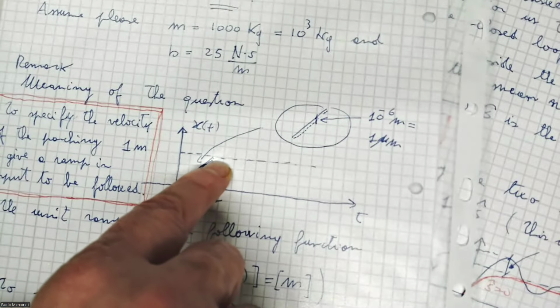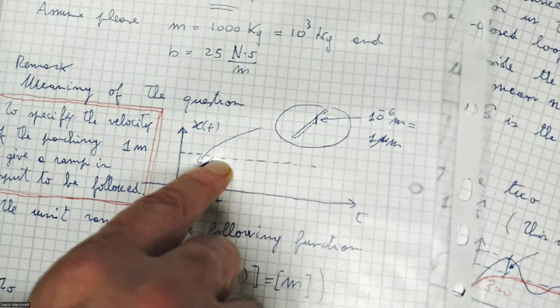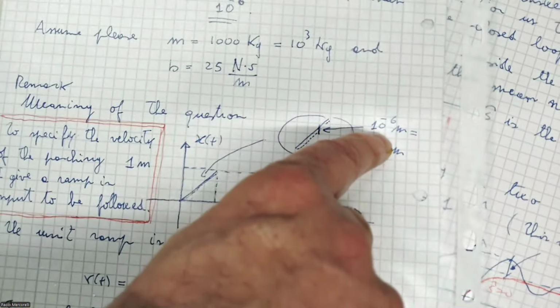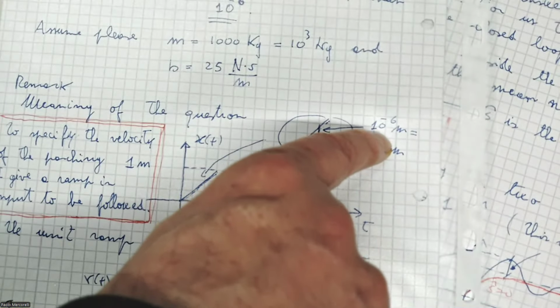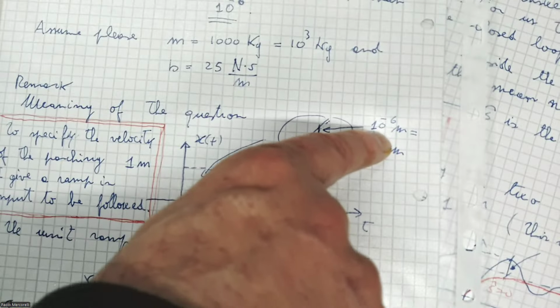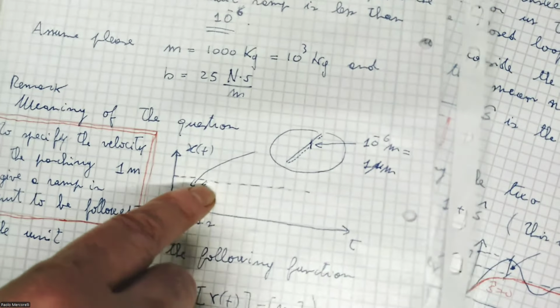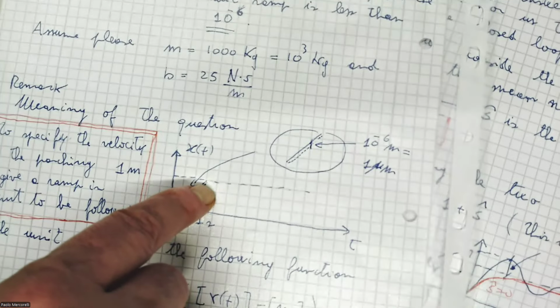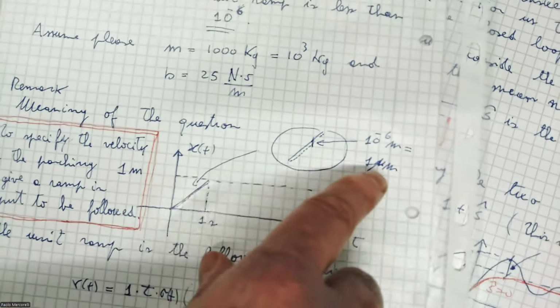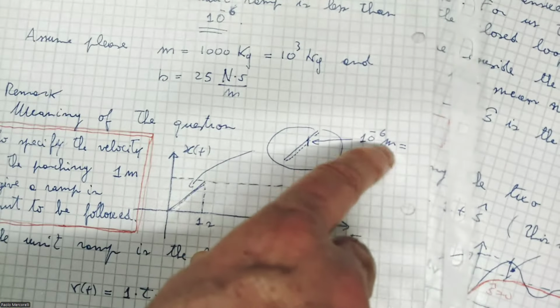Of course, the error which I fixed here is achieved at infinite time. But increasing Ki, I will approximate that in 1 second I am basically at my goal, except something infinitely small larger than this one.